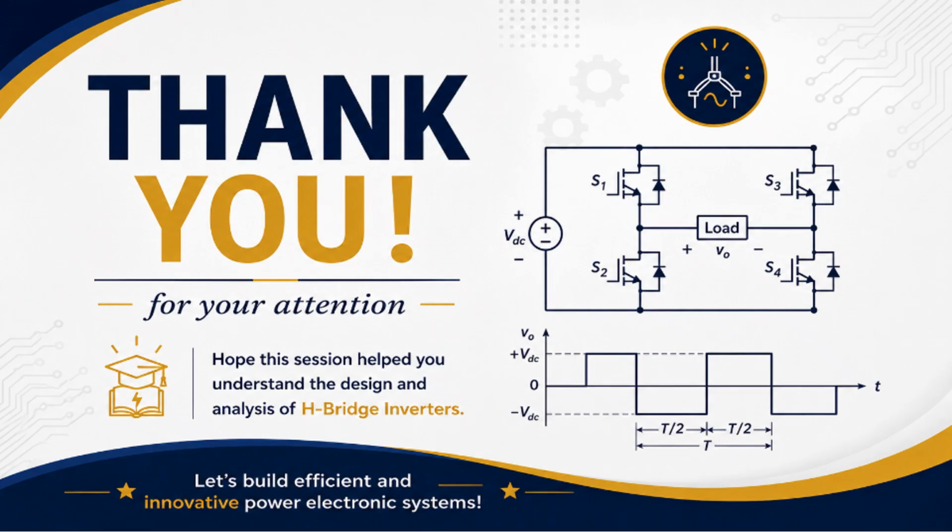So let's summarize today's session. We have completed the H-bridge inverter, which is used for a controlled switch with two legs. This will convert a DC input to a reversible AC or controlled AC. The inverter can generate three possible output levels: plus VDC, minus VDC, and 0. For the case of bipolar, it switches from plus VDC to minus VDC. Control of bipolar is simple, but voltage step is from plus VDC to minus VDC.